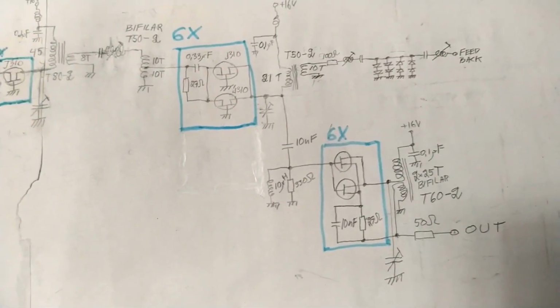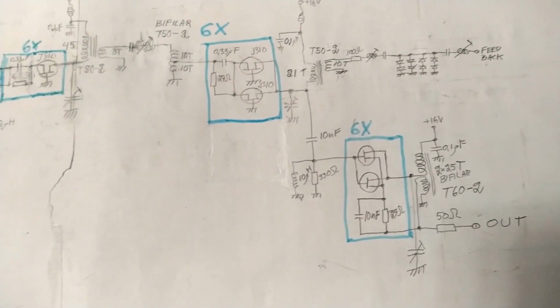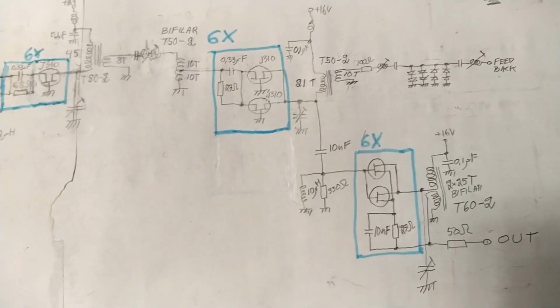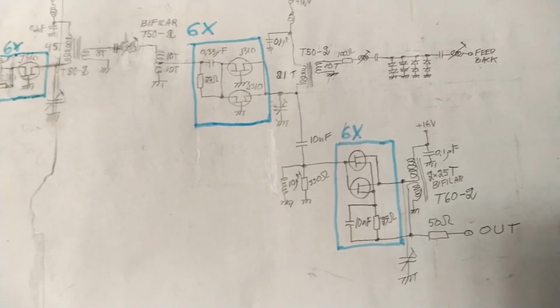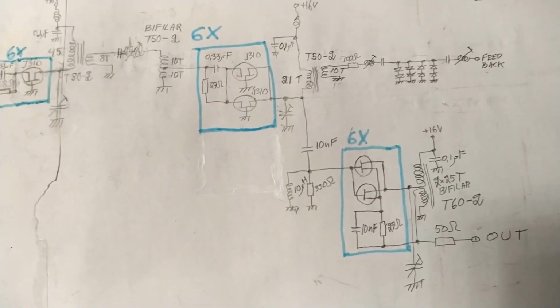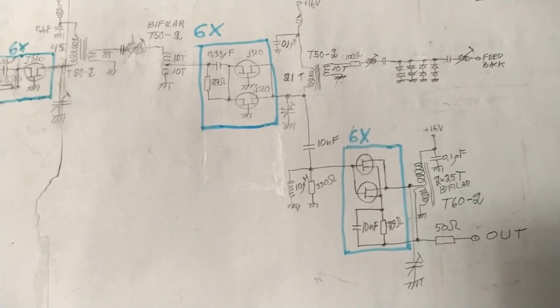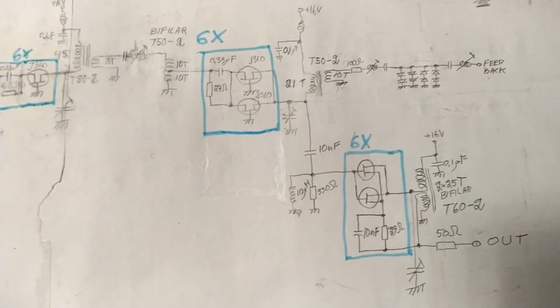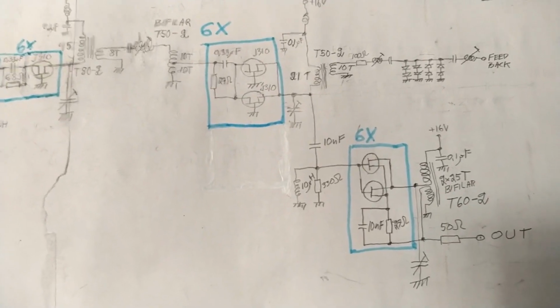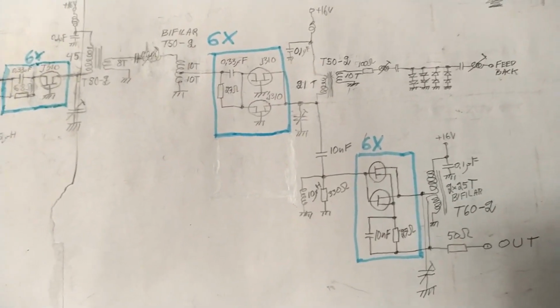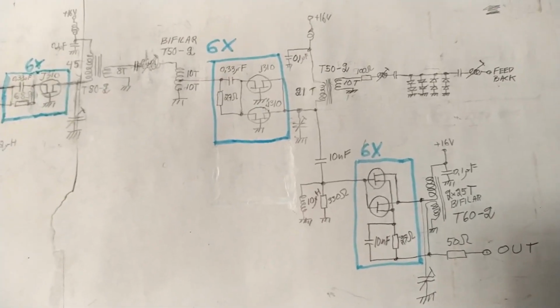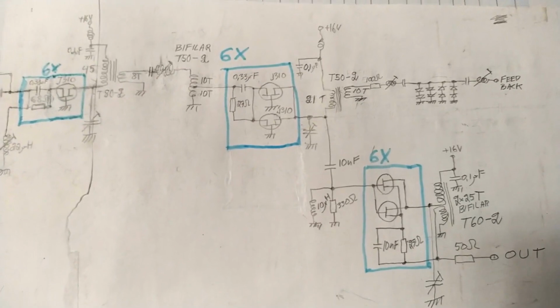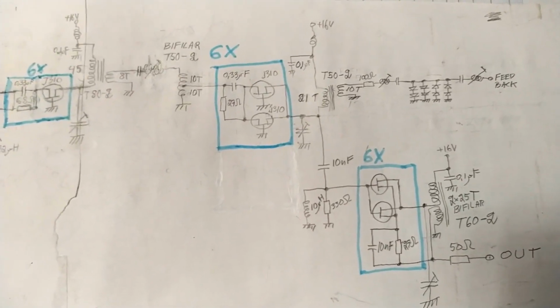Now, my idea about the problem is that all these FETs suffer from flicker noise, and the flicker noise gives rise to a varying supply voltage, because current is supplied through a big resistor, and then there is a big capacitor parallel to the unit at 16 volts.